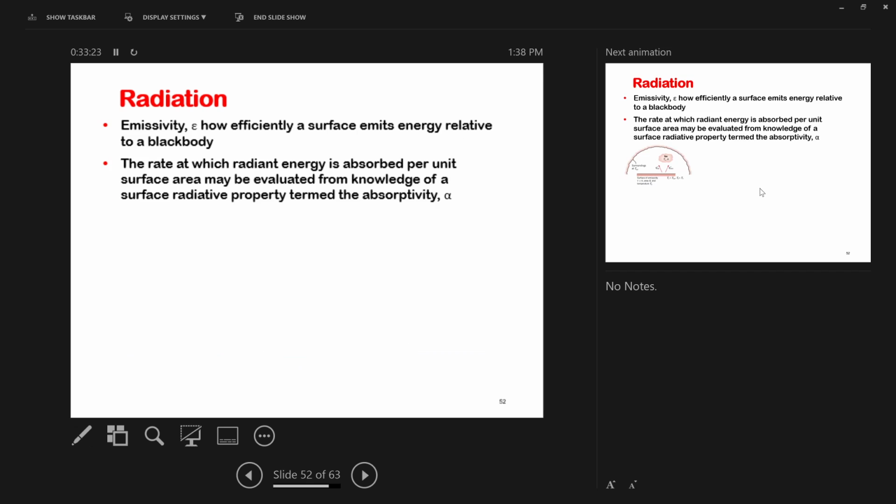But when it comes to radiation, we have another type of energy. So far we have talked about the emissive power. What about the absorption? Some energy can be absorbed by each surface as well. And for that, we essentially have the same theory and same ideas. The only difference is that the non-ideal part of your absorption comes from alpha, or absorptivity, instead of emissivity.